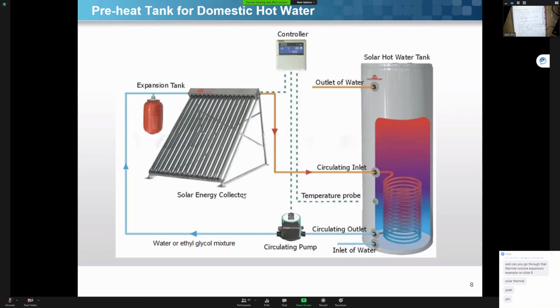For that reason, you need to have enough solar solution or heating solution inside there, like a mixture of water and glycol. At nighttime, it might not occupy all the space inside, but you still have to fill it up. But when it heats up, if the temperature rises with good sunlight, it can increase the temperature a lot. When the temperature increases, they will expand.